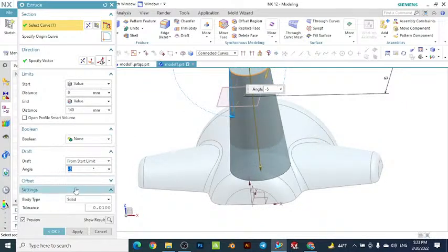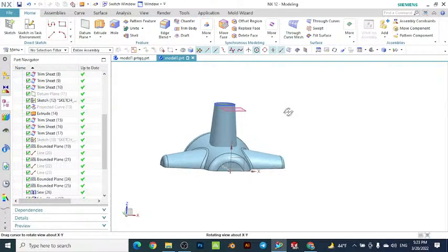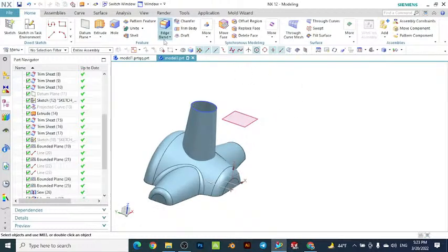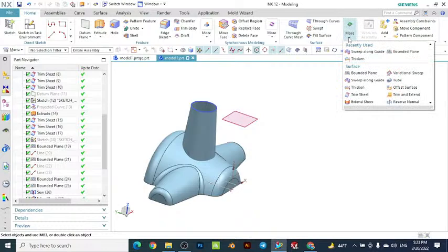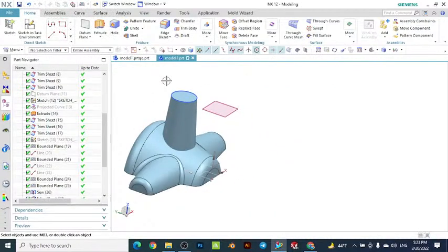So, and make it sheet metal. So press OK here to create our thing. So we created the system. Now we can close the top surface for the beginning. Go to the more function, select the boundary plane and this one. So we closed our system.